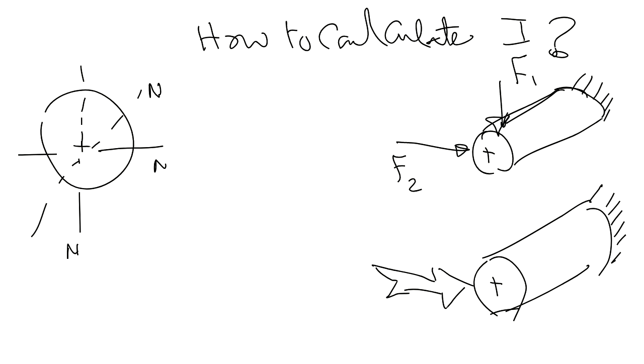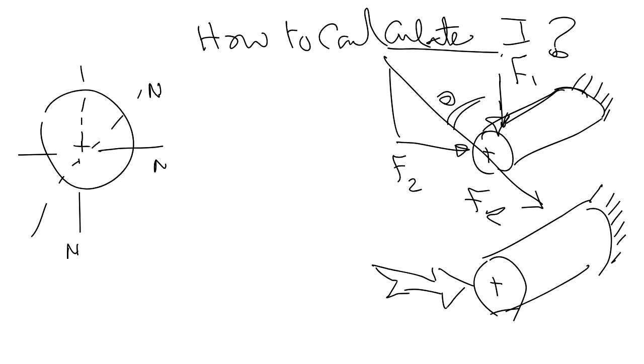See, guys, in a case like this, first of all, we have to come up with the resultant force and find the location of that resultant force. And based on this, we can say it's okay. If the resultant force is moving all the way to the back, then it will be accompanied with a moment. You see the moment, guys? You see how it's taking the same direction of the force? And in this case, your neutral axis will be perpendicular to that line. This is why in a simple case like this, if your force is here, then if you move your force all the way back to the back cross section, you will end up with a horizontal moment like this one.